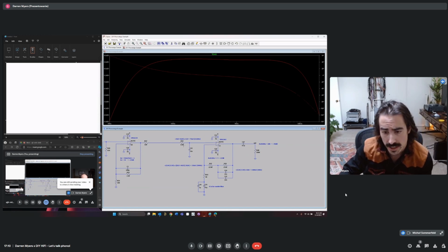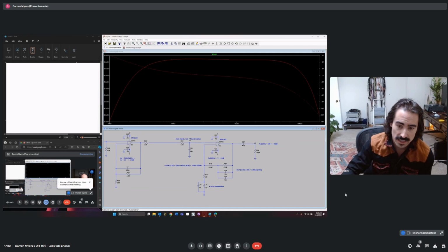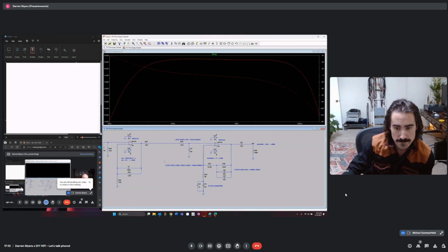It loads it at high frequency. Yeah, so at high frequency you start getting lower impedance and it starts to kick in, but at low frequency, it's really high impedance. Okay. I always found that confusing, so I thought that we should mention it.